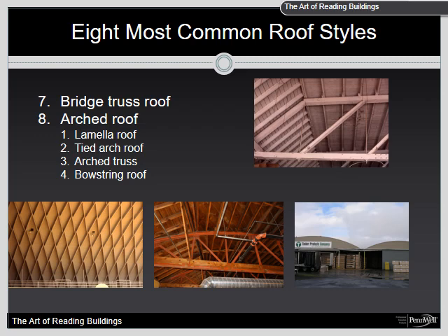Strengths. Bowstring roofs use large timber members and bolted connections and are well constructed. When exposed to fire, early structural collapse should not be of primary concern like the bridge truss roof. It usually fails in sections depending on the type of fire and the structural integrity of the roof. The strong area is at the perimeter of the building.